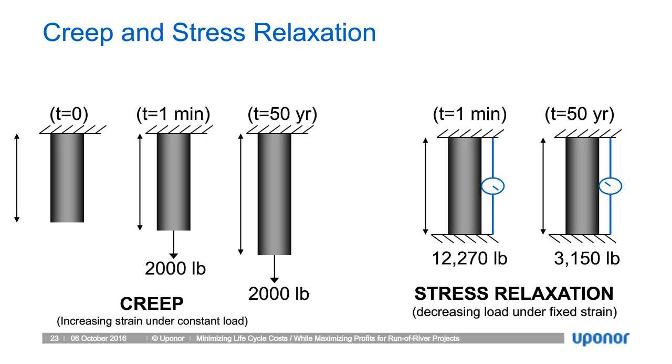Creep and stress relaxation of HDPE is another important aspect of the material. You see here under creep, increasing strain under constant load, that yes, the material will creep and will extend. So it is reacting to stresses or strains being applied to it. The stress relaxation is a decreasing load under fixed strain.